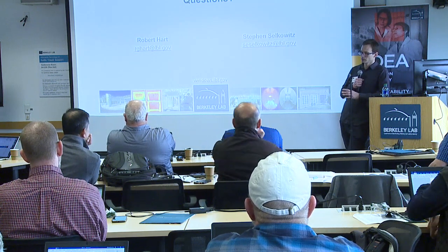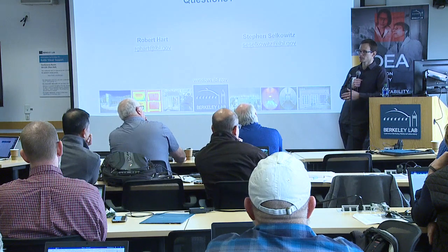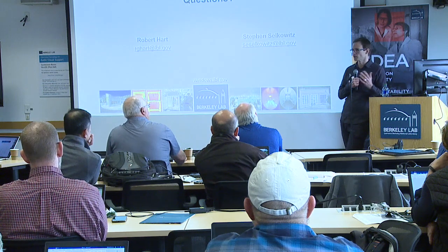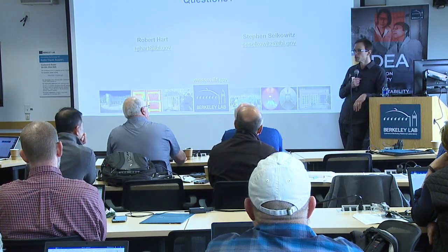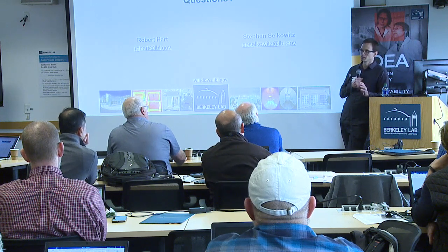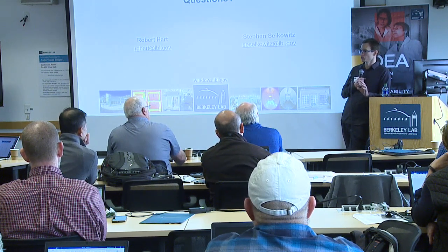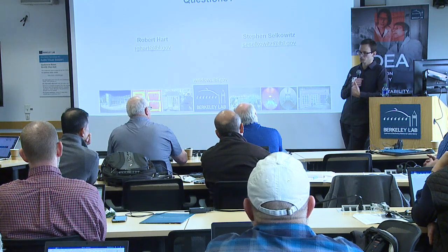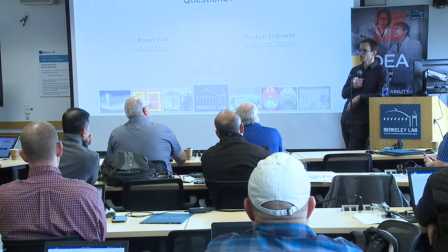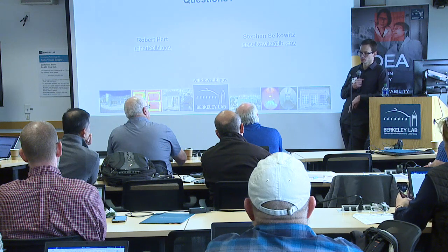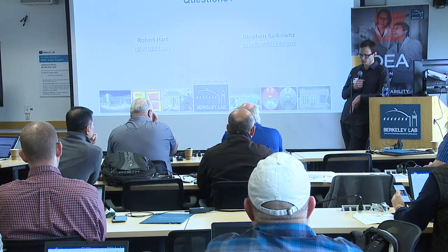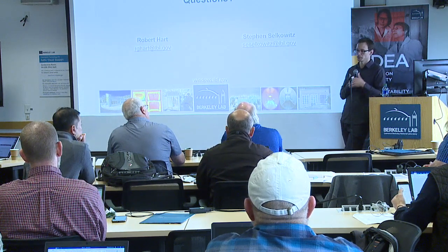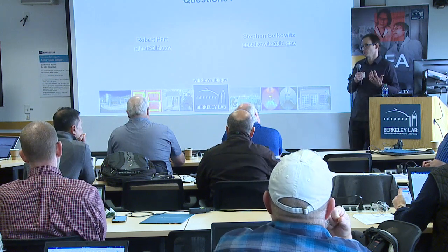The issue of argon leakage, I guess there's two. There's durability of a seal, and then there's this gas leakage. The gas leakage issue has generally been solved by sealant manufacturers 20 years ago. If you have older windows, there was a period about 20 years ago where the sealants weren't good, and then they fixed it. Now argon generally stays in the unit. Almost all windows sold now have argon in them, just by standard practice. That's part of their automated equipment. They just put it in. Krypton, there isn't as much data about it. The sealant manufacturers tell us it's about the same performance, but you don't know.